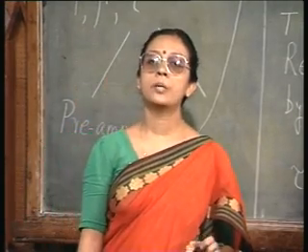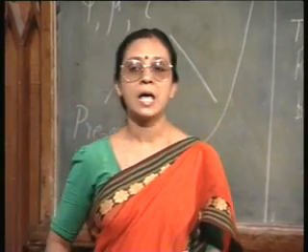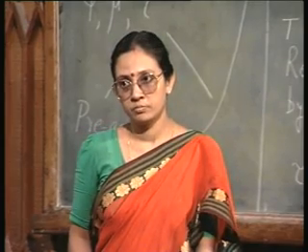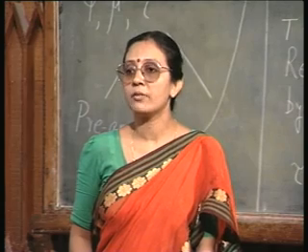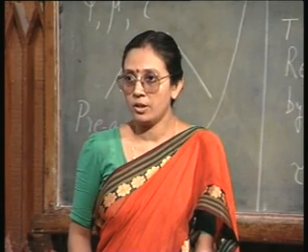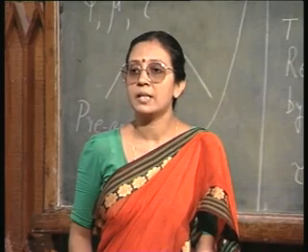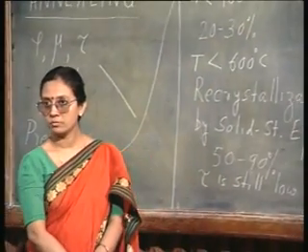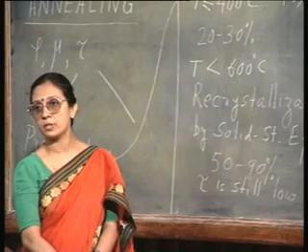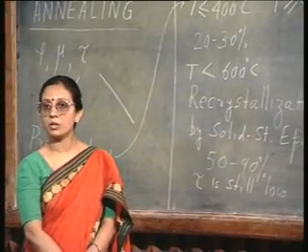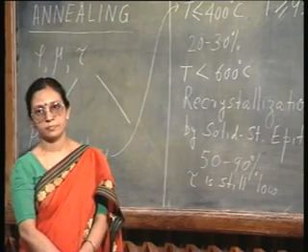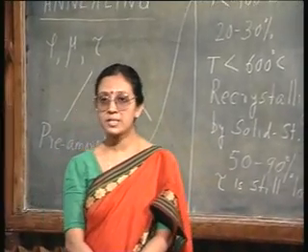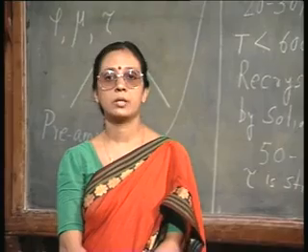So, now depending on what your requirement is and what your obligations are, you can choose your annealing schedule. If you can live with low lifetime, and you would like to maintain the annealing temperature and time low, then this phase would be sufficient. On the other hand, if you are really very particular about lifetime recovery, you have no other option but to go to high temperature. So, this is about the pre-amorphized material, in which case by 600 degrees centigrade you have considerable carrier activation.